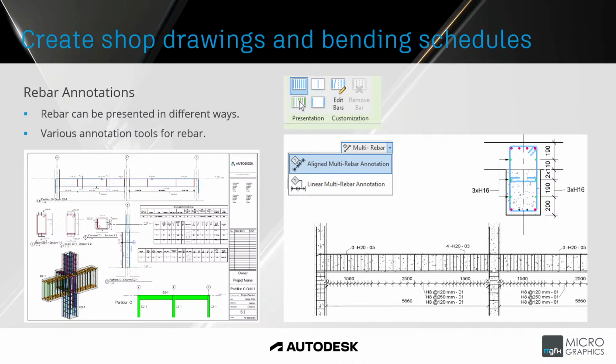You basically just click on the rebar, place the annotation, and obviously there's styles involved like any other kind of dimension in Revit, where you can adjust the style, how the rebar looks, and what it displays. Does it display the bar thickness or the diameter, how many of the items, etc.? That can all be defined in a particular style.